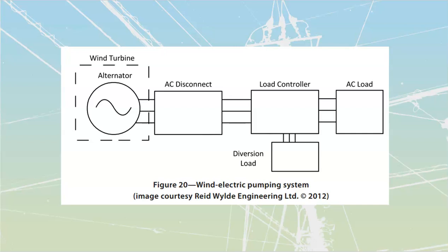Standalone wind power systems are going to be commonly used for remote little sections. We'll use them for wells in a lot of cases because we can have an electric pump down a deep shaft well pump. Doesn't require priming or anything like that. If you've got a surface-mounted wind pump, you do have to keep it primed, and if that dries out, it causes problems. But we commonly will see these used for small scale, just a single type of load.